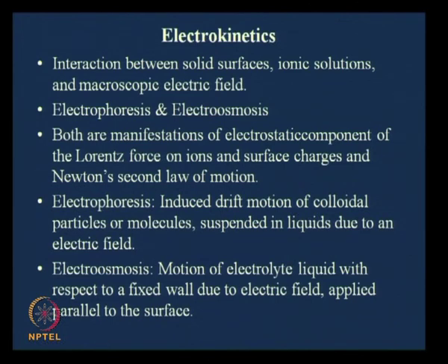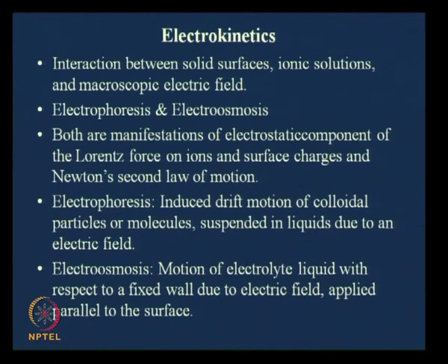Now, these both are manifestations of the electrostatic component of the Lorentz force on ions and surface charges and Newton's second law of motion. So, you are looking at first of all the electrostatic forces, and also you are looking at Newton's second law. So, it is a mixture of both. Basically, our governing equation in this scheme of things would be the Navier-Stokes equation. However, we have an additional body force term arising from these electrostatic interactions. So, basically we are working within the framework of the Navier-Stokes equation only with an additional body force term.